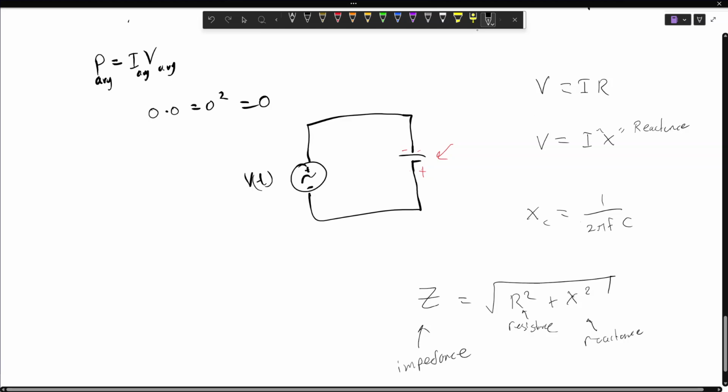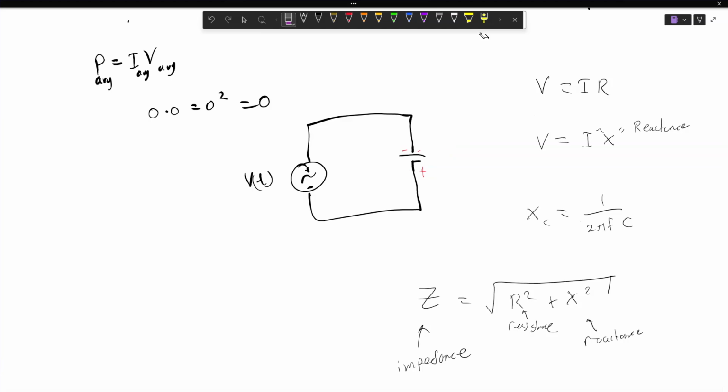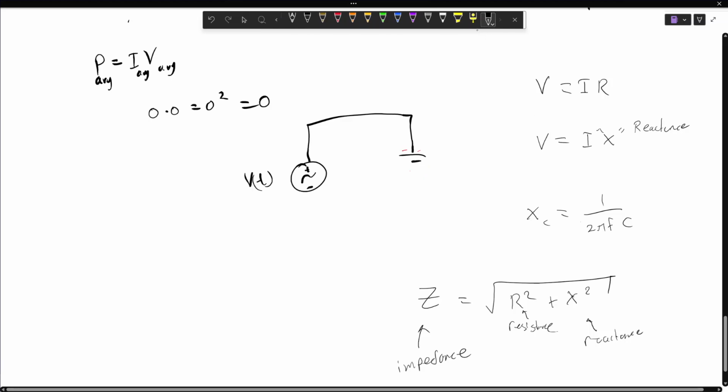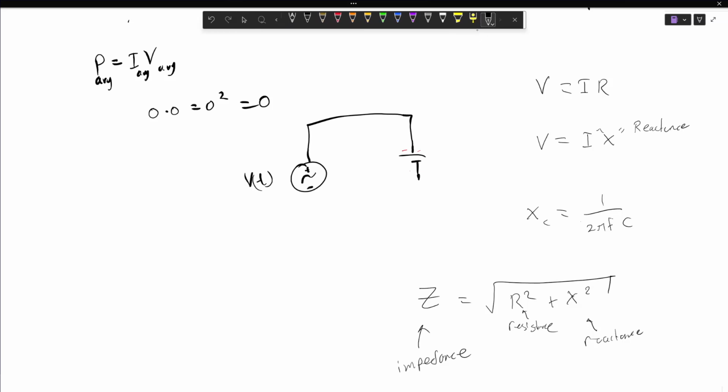This is just that high level view of what we'll be able to do with some of these tools, which is build out some filters. So if I have a resistor that goes into a capacitor, or sometimes we'll switch the order, we'll be able to attach some probes here and have either a low pass or high pass filter, as we call them, because they're able to pass on voltages at high frequencies or at low frequencies.